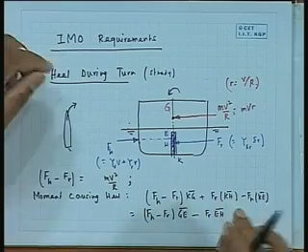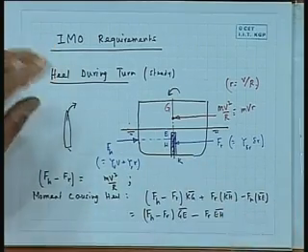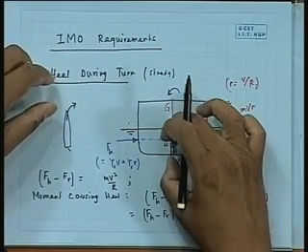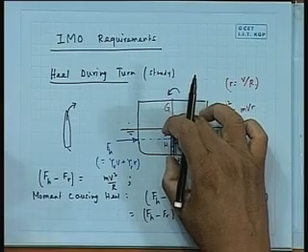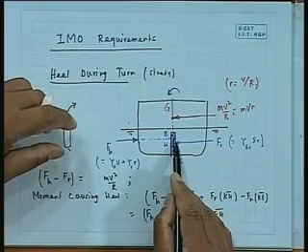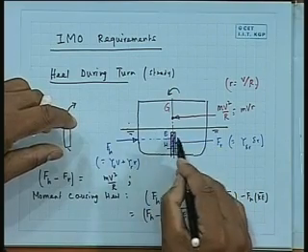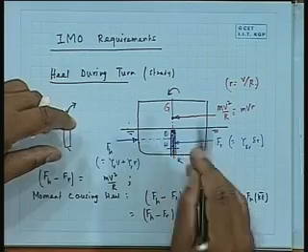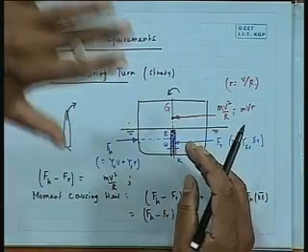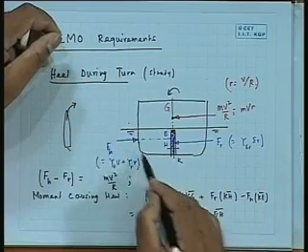The main reason for writing this is that it turns out for many ships EH is very small. Why? Because the rudder will typically be over the entire draft, mostly slightly less than the draft. So it will come about the middle of that. As you can see, the rudder is not really ending at this point or at this point. Normally, you try to make a rudder because you want more area, so you increase the rudder up to more or less the waterline, the design waterline. And this part will also come at more or less the center of that.